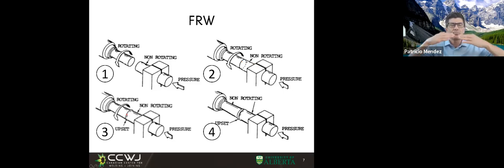And as you put pressure, they form what is called an upset, and some of the material comes out, forming some sort of a scarf or a lip, right? And at some point you stop the motion. If it is driven by a transmission, you stop the transmission, and if it is driven by inertia, it will eventually run out of inertia.